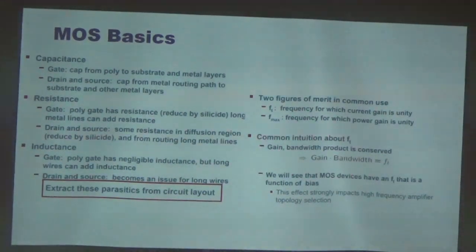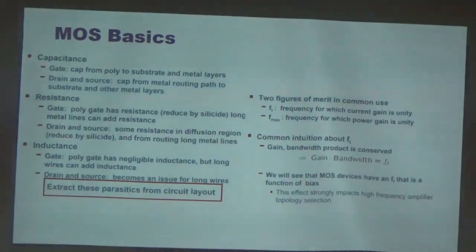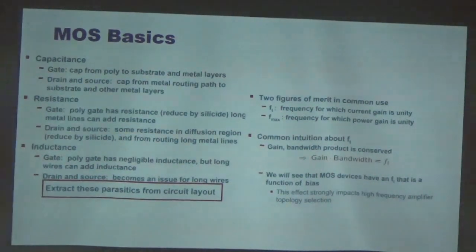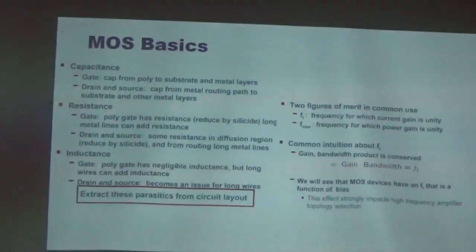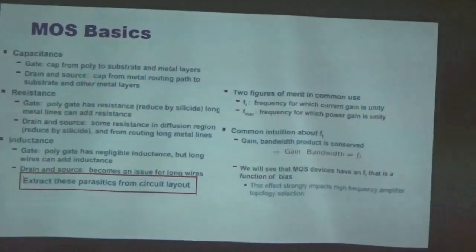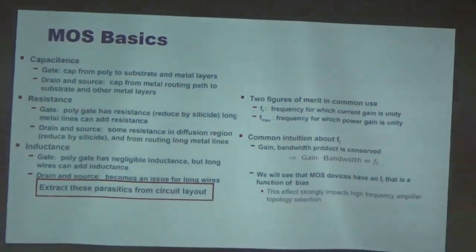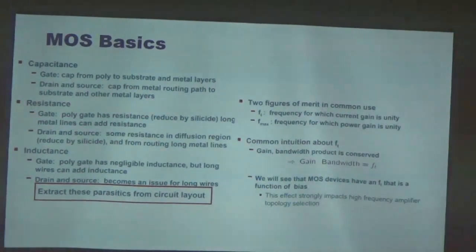So the gain bandwidth of any analog circuit which you design in your course project or your major project will every time be limited by your FT. So there is a direct relation between FT and your gain bandwidth product. So if you want to design any circuit with higher gain bandwidth product, you need to increase your FT of the technology.